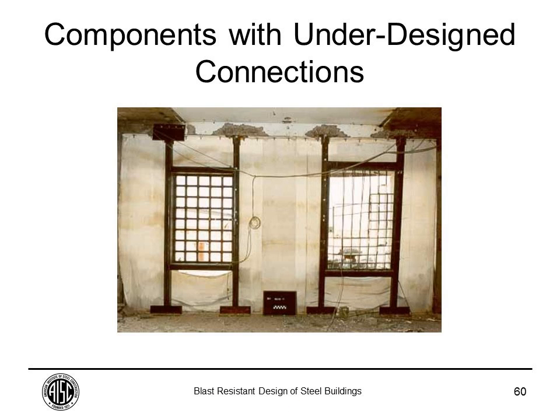Here's just a quick picture. I just wanted to show you what a failure of a connection looks like. These are some old tests on some steel frames. This is a very typical retrofit for windows on existing buildings where the wall cannot take the loads. So you retrofit them by putting steel frames behind them, and the windows connect directly to the frame.